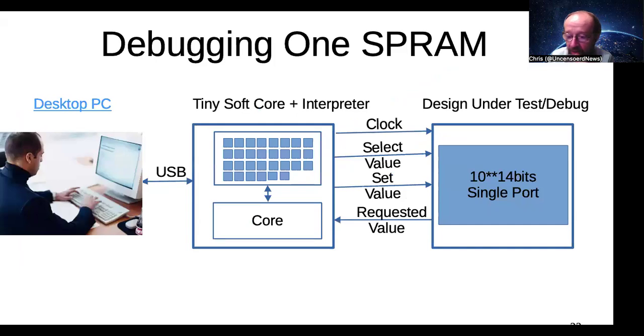And okay, clearly something is wrong there. I did a single port. And what I was able to demonstrate is that warm reboot simply does not save it. You write a script to copy the data in, you do a warm reboot, all the data, boom, gone. A lot of people have tried to do this. Actually, nobody had succeeded. Even when we reported this through the board vendor to priority partner technical support at Lattice, they had never heard of anybody who actually succeeded in doing this. But because I had such a good test environment, I could demonstrate that the single port was not working.